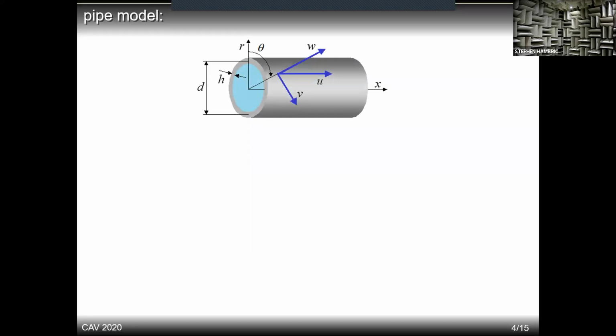As I said previously, we need a model to carry out smart pipe analysis. A generic model of a pipe filled with a homogeneous fluid or gas can be constructed analytically. So the model depends on a number of input parameters, like the material constants of the wall, the constants of the fluid, and the diameter and thickness of the pipe.